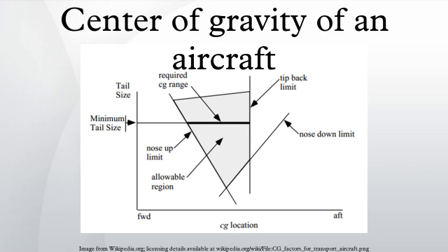Center of gravity out of range: when the fore-aft center of gravity is out of range, serious aircraft control problems occur. The fore-aft CG affects longitudinal stability of the aircraft, with the stability increasing as the CG moves forward, and stability decreasing as the CG moves aft. With a forward CG position, although the stability of the aircraft increases, the elevator control authority is reduced in the capability of raising the nose of the aircraft.